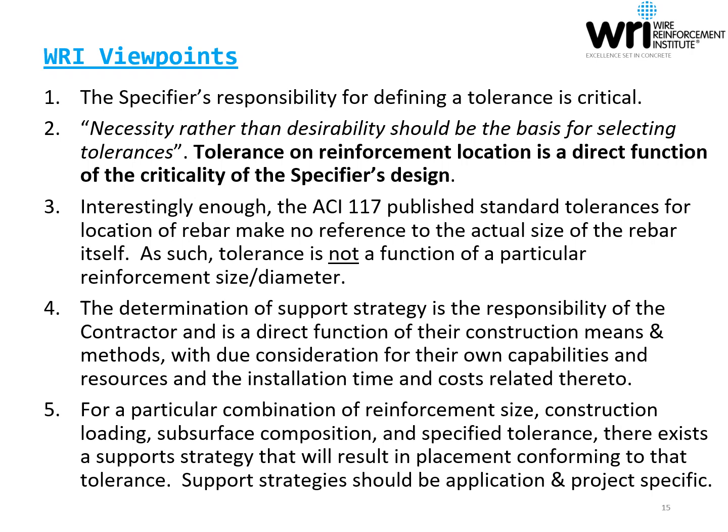And fifth, for a particular combination of reinforcement size, construction loading, subsurface composition, and specified tolerance, there does exist a support strategy that will result in placement conforming to that tolerance. Support strategies should be application and project specific, and some support strategies may be more laborious and challenging than others, depending on the tolerance stringency that is compatible with a particular design location.